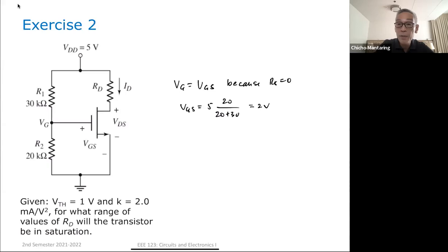In fact, NMOS and PMOS together, you call that CMOS, complementary MOS, when you have both NMOS and PMOS in a circuit. And CMOS is now the most common type of circuit that you find in integrated circuits or in microchips. And then you have the depletion type also.